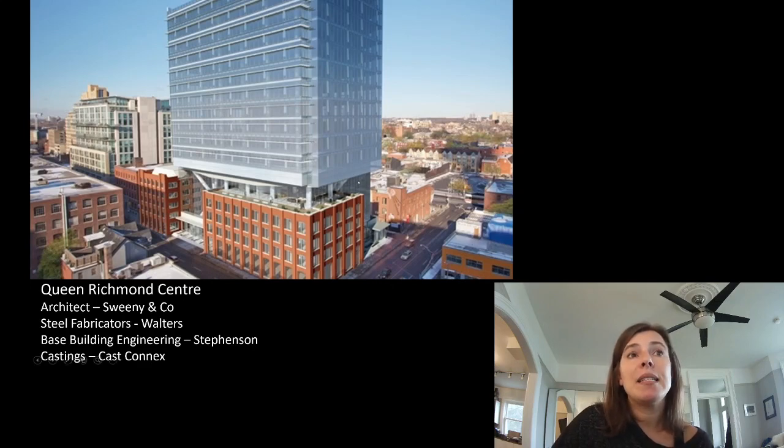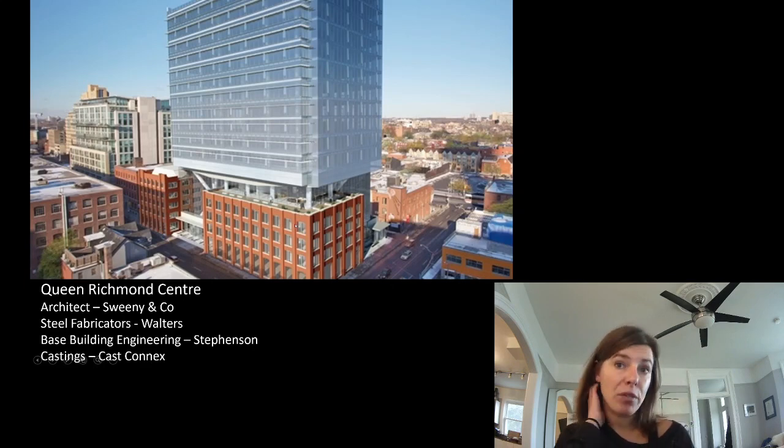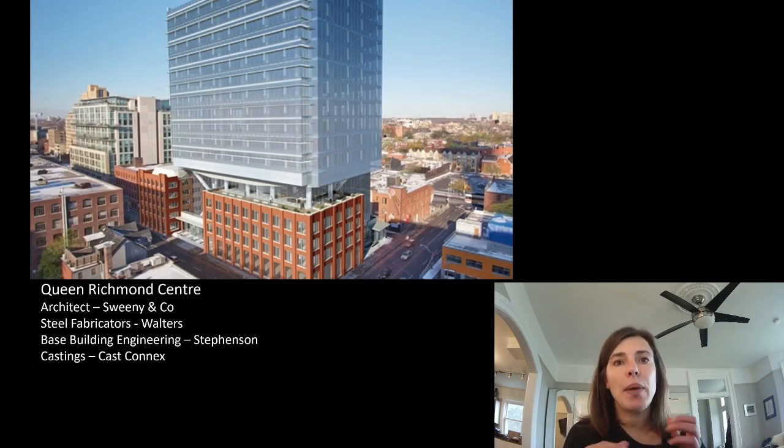So this needed to be a glassy atrium where you could view this structure, and minimal work could be done to this facade. It wasn't strong enough to use as a lateral system without overloading it, so they needed to be able to punch through it to get the loads down to the ground.